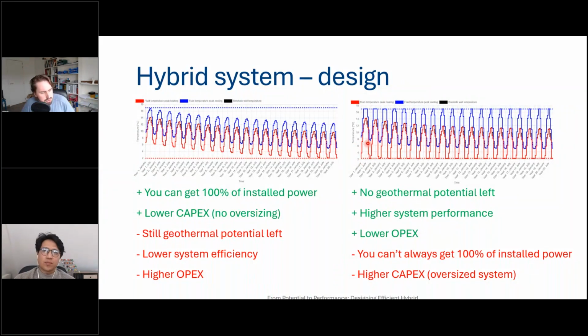So that in these first years, we're also going to touch the temperature limits, so the minimum temperature. By doing so, we can exchange as much energy with the ground. But as we saw in the example, we need 500 kilowatts in order to tap into this potential here. But year after year, we cannot use that power anymore because we are limited by that temperature limit. And that's basically the difference.